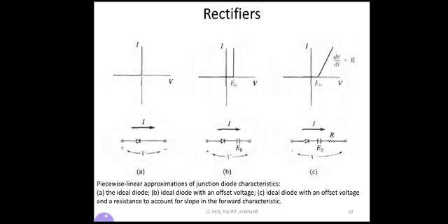So an equivalent circuit for a device is a circuit that represents the device behavior. The equivalent circuits are shown in the diagrams below. In the first diagram, the diode is forward biased, that is, positive is applied to the anode, the positive of the battery, and negative is applied to the cathode. Like this we can make it forward biased and reverse biased.